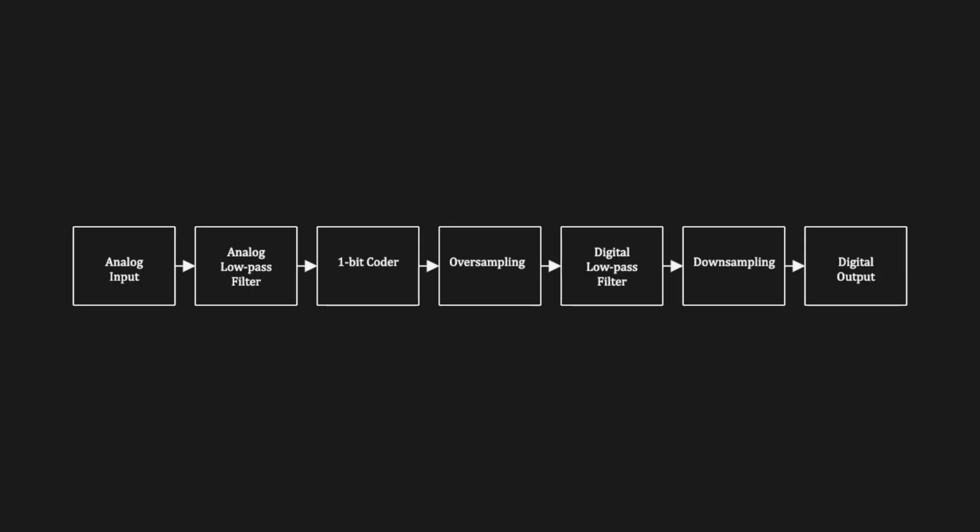Compared to SAR converters, oversampling AD converters offer much higher accuracy. They spread quantization noise far beyond the audio frequency range, leaving less noise within the audible band. Their built-in digital filters not only prevent unwanted noise generation, but also remove frequencies above the audio range, producing a cleaner and more accurate digital signal.